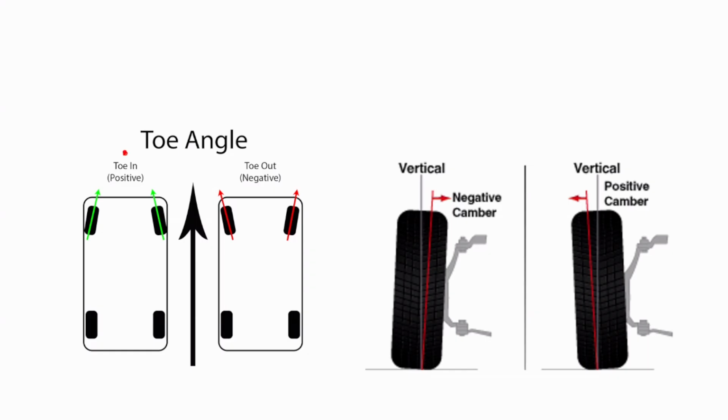These tires are heading towards some sort of center, which is located at the outer area, right? So let's say the center is here. But in the toe out case, you can see both tires are directed outward, right? So we call it negative toe angle. So what do you think about these angles? Which one is better? Or do we need to have parallel wheels?